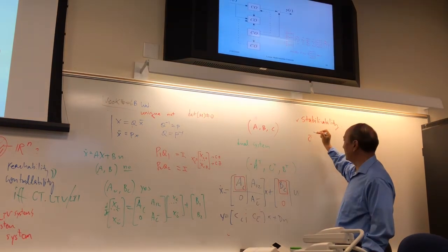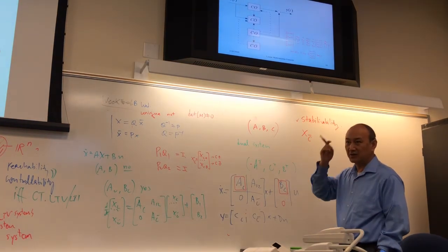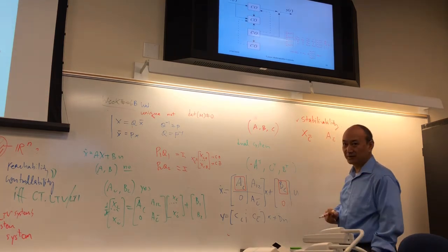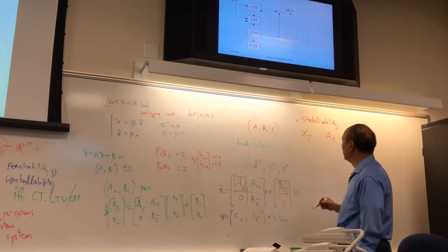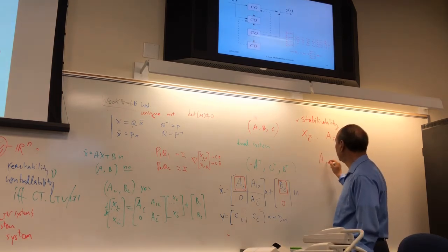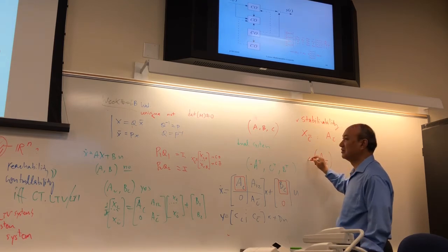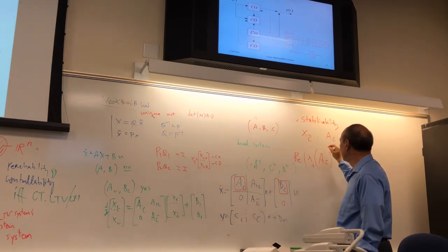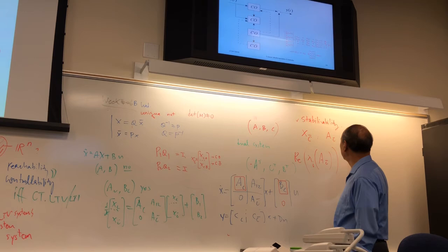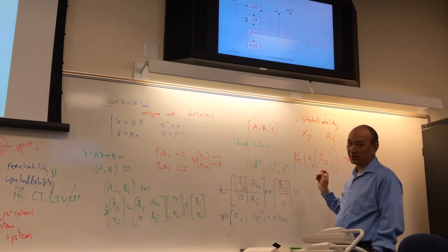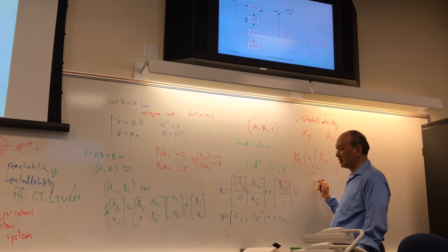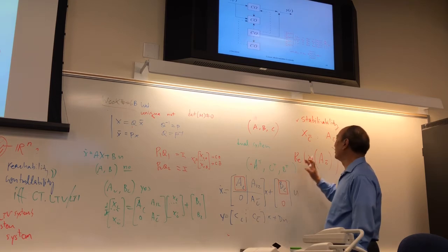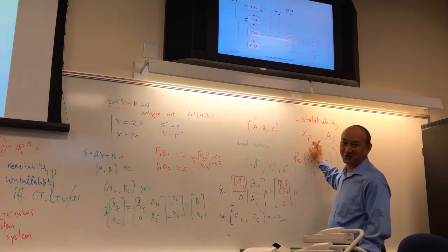So it's the uncontrollable subspace. Then you also have a matrix, A uncontrollable. And if this A uncontrollable has an eigenvalue with real part greater than 0, that means that mode is inherently growing and unstable, and you cannot do anything about it because it's not controlled.